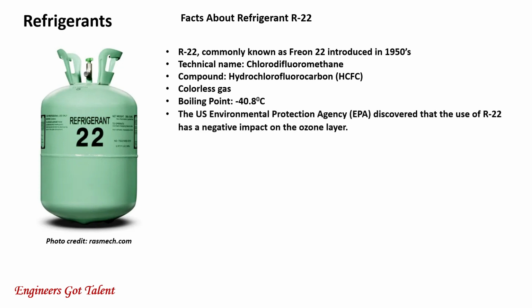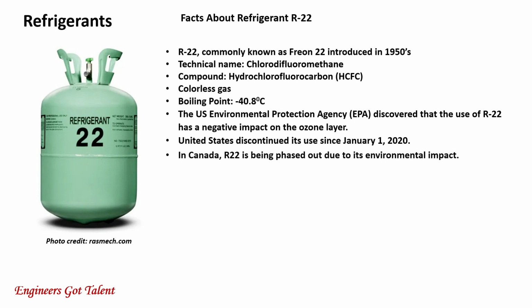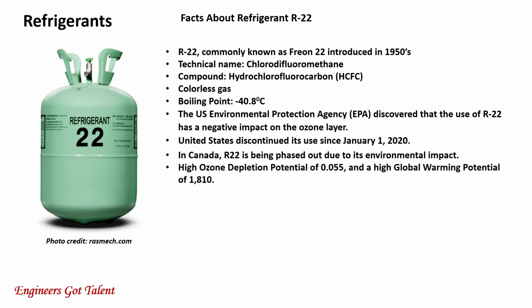The U.S. Environmental Protection Agency discovered that the use of R22 has a negative impact on the ozone layer. The United States discontinued its use since January 1, 2020. Here in Canada, R22 is being phased out due to its environmental impact. It has a high ozone depletion potential of 0.055 and a high global warming potential of 1,810.